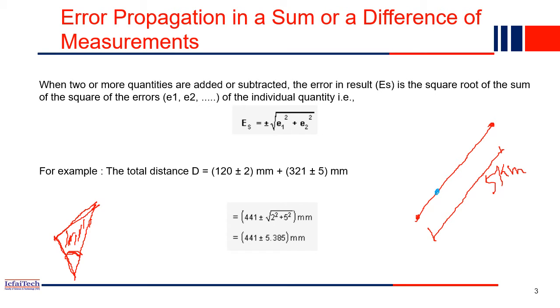Maybe we can make some intermediate points. So this is one point, this is another point, this is another point. Like that, in the middle we normally take some intermediate points. From here, first we find out what is the distance here, then again we find out the distance from here to here. Like that, we divide the entire long distance into multiple small distances, and from there we find out the distance of each segment. So basically we are adding the lengths, adding the measurements.